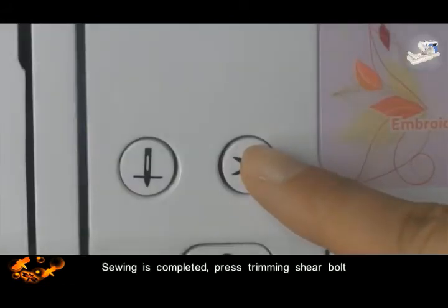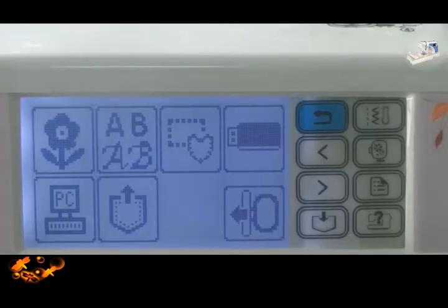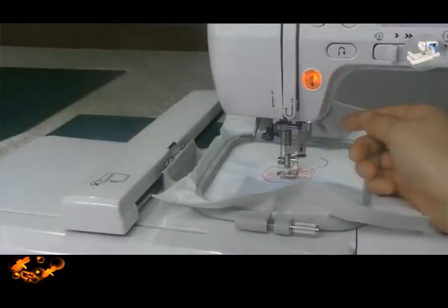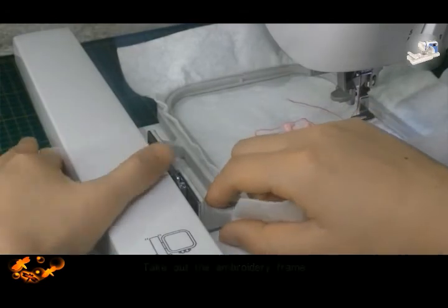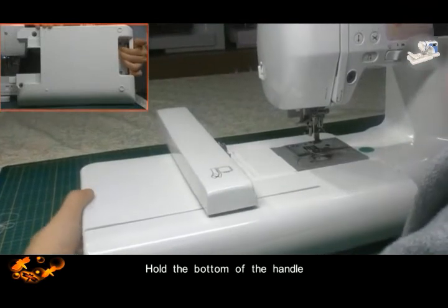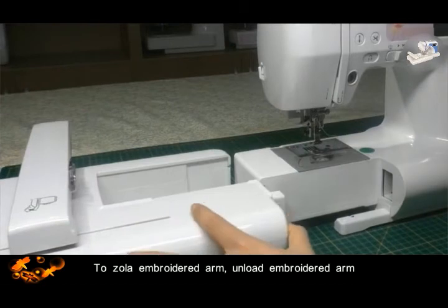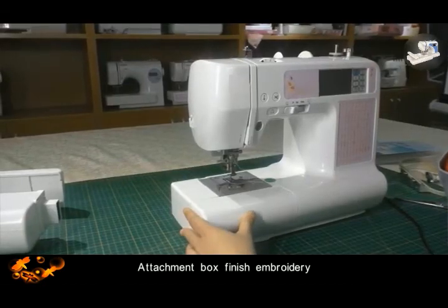Sewing is completed. Press the trimming shear button. After completion, press the key to move the frame out, and lift the presser foot. Make the embroidery arm move out automatically. Take out the embroidery frame. Hold the bottom of the handle and remove the embroidery arm. Unload the embroidery arm. Attachment box: embroidery finished.